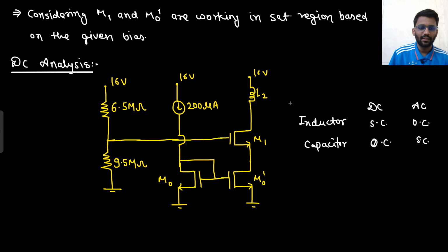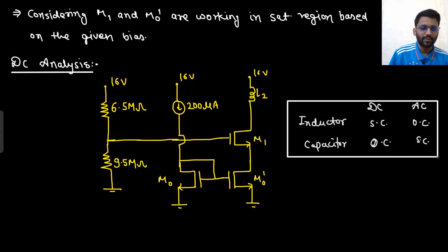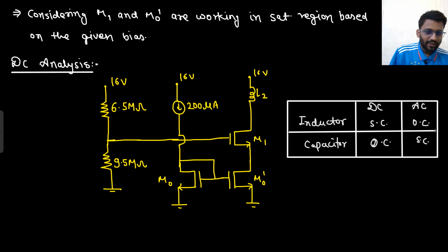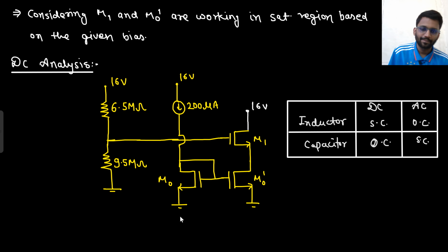Just the opposite, right? Because they are inversely proportional when it comes to the frequency response. So for omega equal to 0, the inductor will provide 0 impedance and the capacitor will provide infinite impedance. For omega going to infinity, the capacitor will provide 0 impedance and the inductor will provide infinite impedance. So here the inductor will be shorted. Well and good.